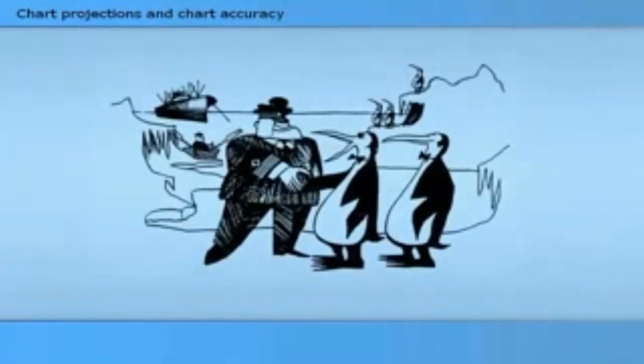Remember that no transformation is perfect, because both the original datum and the datum to which positions are adjusted have inherent weaknesses that vary over their area of coverage. The parameters used within GPS receivers for the transformations from one datum to another are likely to be mean values for the whole area, and their application, particularly in the extremities of the area of an inaccurately defined datum, could introduce errors of hundreds of meters.